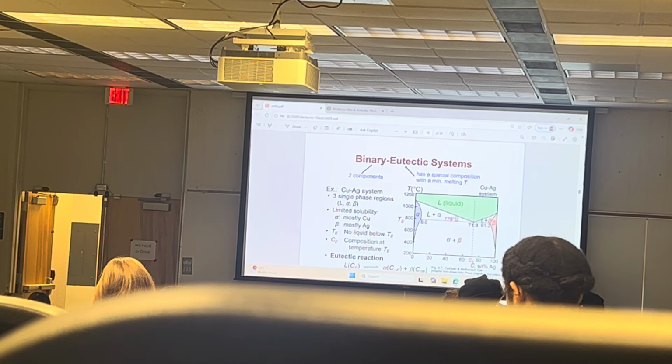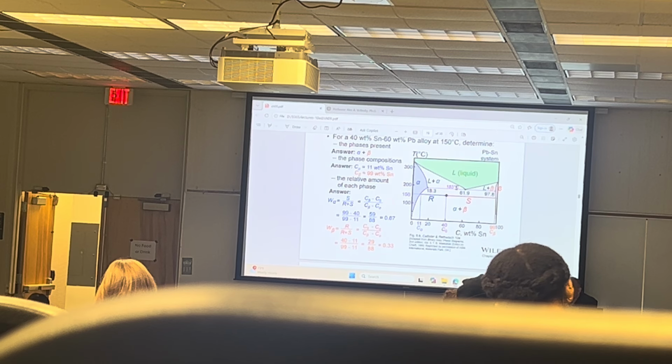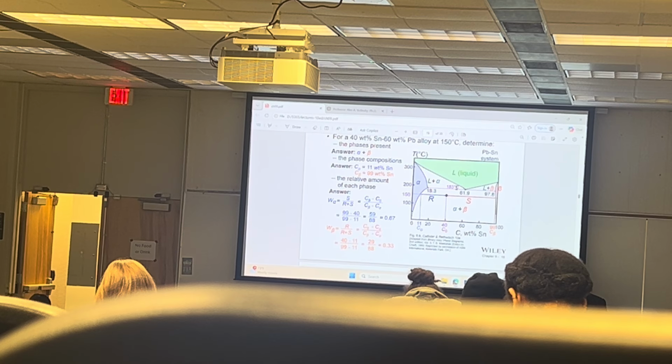And you heat them up. And you only need to heat them up to 183 degrees centigrade. A little bit more, maybe under 200. Because if you heat this thing above 200 degrees C, you are going to destroy your components, your chips and whatever, capacitors, resistors. They cannot survive this high temperature.